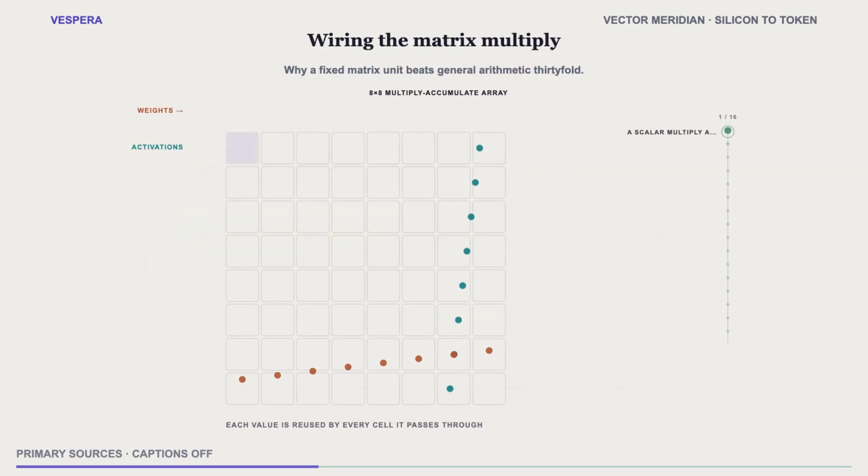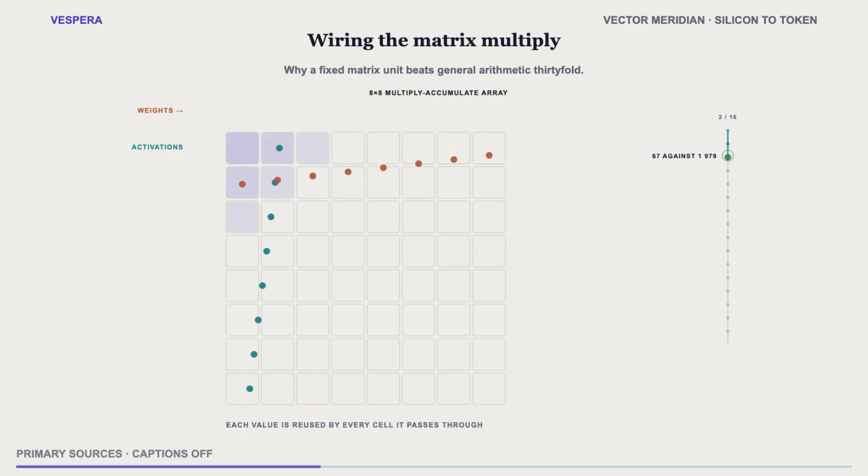There is one more piece of hardware on the die, and it is the piece that changed the economics of the field. We established that a multiplier's area grows roughly with the square of its operand width, and that matrix multiplication has high arithmetic intensity because each operand is reused many times. A tensor core is what you build when you take both facts seriously at once. Instead of a lane that multiplies 2 numbers, build a unit that multiplies 2 small matrices and accumulates into a third, an entire 4x4x4 operation, or larger, as a single instruction.